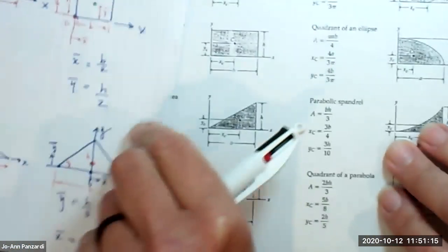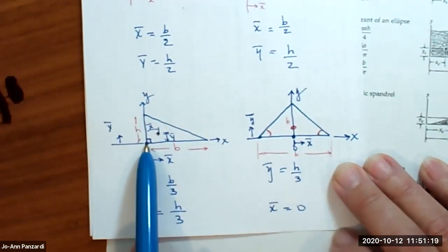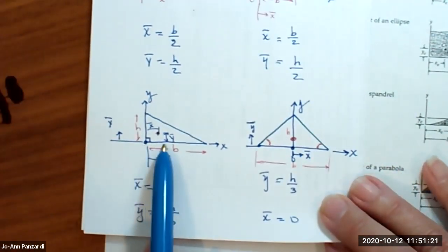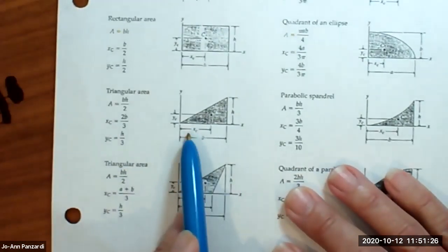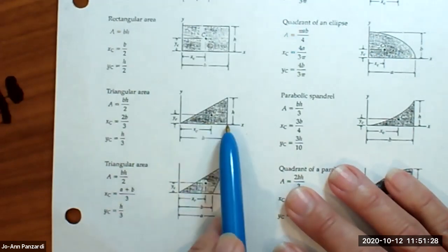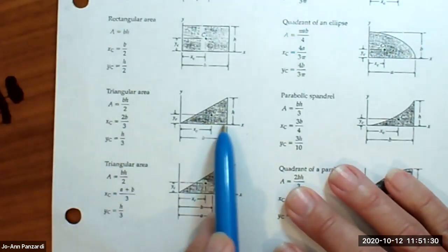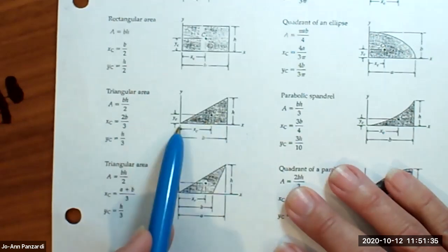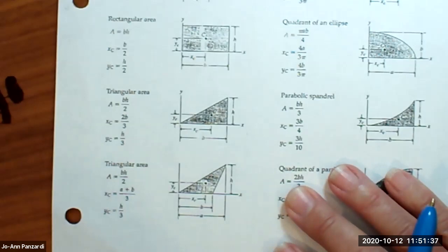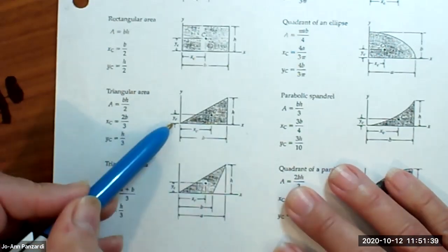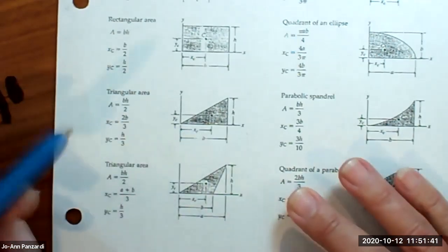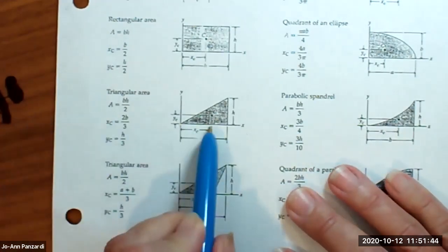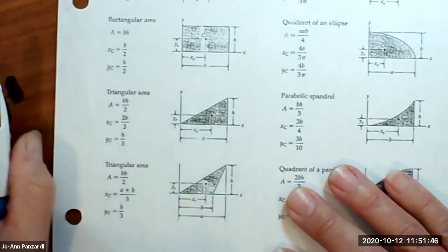So just to check in again, the centroid here measured from this corner was 1/3 in and 1/3 up. But since the X and Y axis is set up at this end rather than what I called the fatter end, we're actually finding that the centroid is 2/3 in and 1/3 up here. 2/3 over and 1/3 up. I think I just made that mistake. It's 2/3 over, but it's still 1/3 up. Okay?